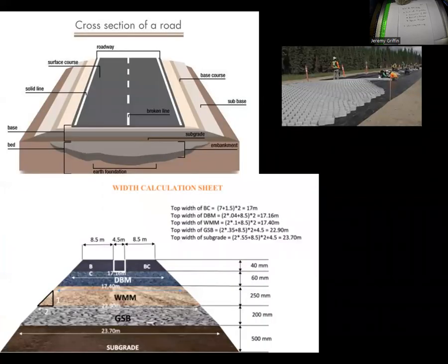And finally, roads. So if you are designing a road system, what does this look like? There's this whole structure underneath the road. You just see the top pavement, right? But there's this whole structure underneath it. So you want to put large materials, large rocks and boulders down far below, and then successively smaller materials until you get to the top. And most roads are made out of, or I want to say most are asphalt pavement, asphalt concrete, although you could use Portland cement concrete too, but asphalt is quieter, feels a little bit nicer to drive on, right?